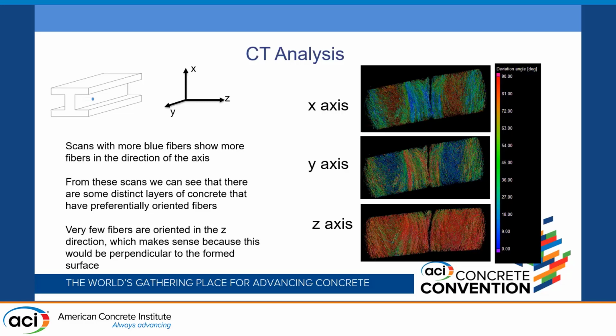Oh yeah, no, we're going for repeatability. This is not like one scan and we took our best data. When we're going into our NDT data, we're having averages of scans. And so we'll rerun those over and over again. And so I guess like left to right here, were there several scans along this? No, this is the web. Oh, I see what you're saying. So this is our CT analysis, not our NDT analysis. Correct. So this is just a single core that you're seeing, actually a CT image of the fibers themselves.